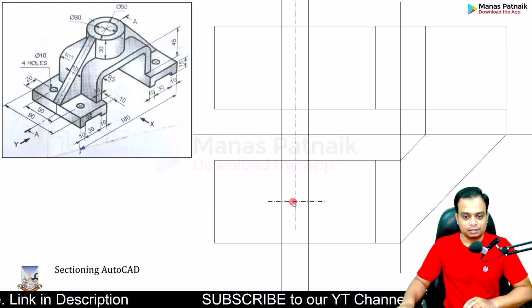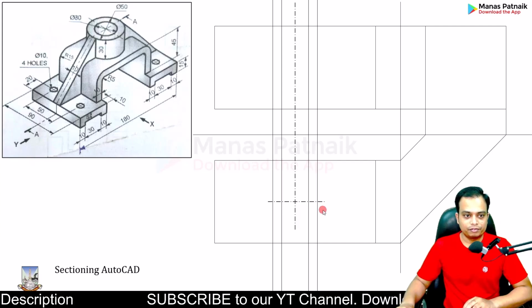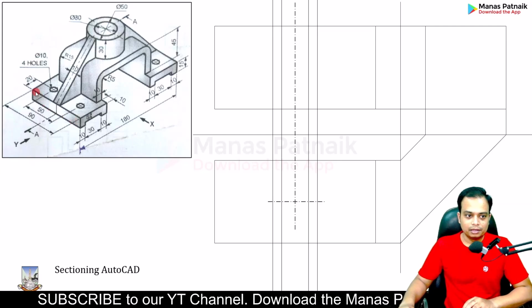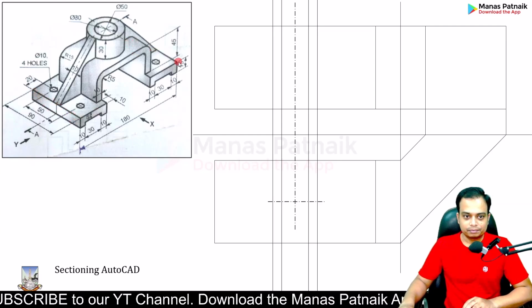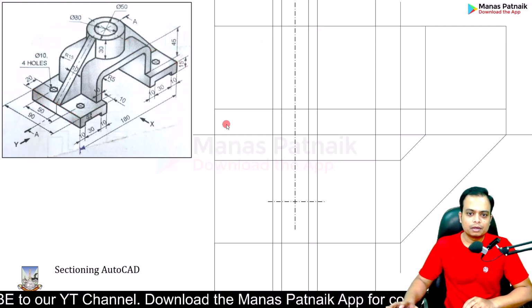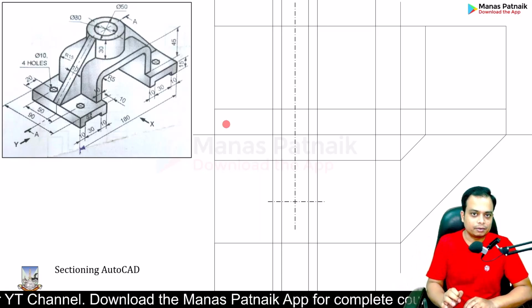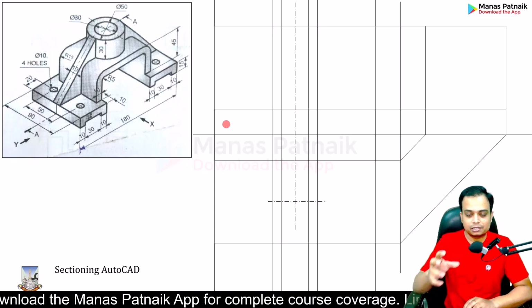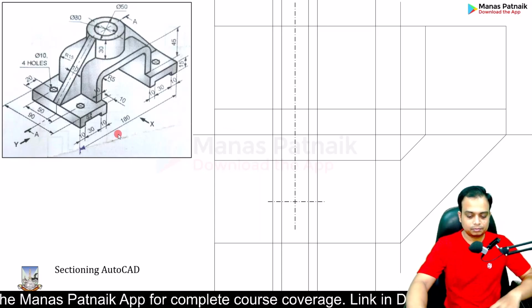15, 15. Similarly, the outer circle, 50 diameter, 25 to the right, 25 to the left. Okay. These two edges, this way. All the guidelines that I'm making right now should be done with the help of a very light pencil, a 4H pencil, very grayish stuff.